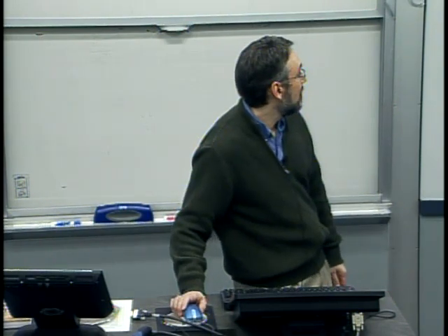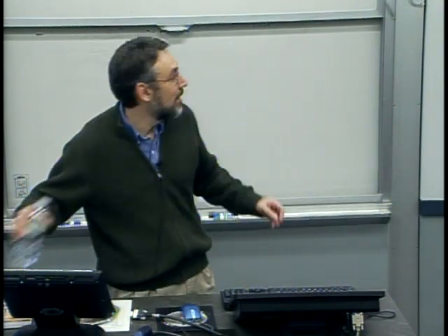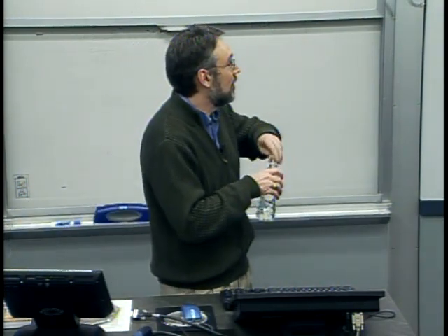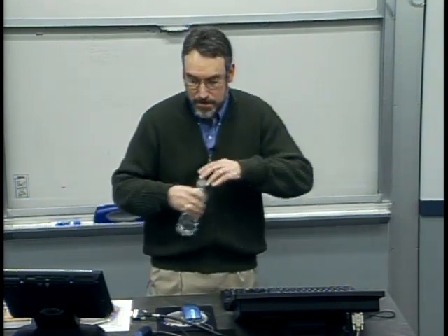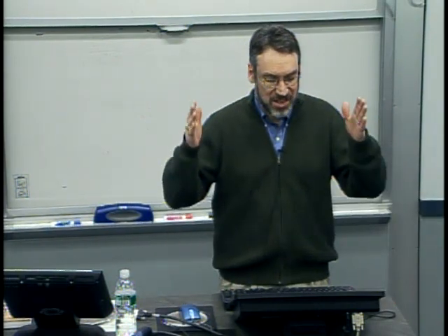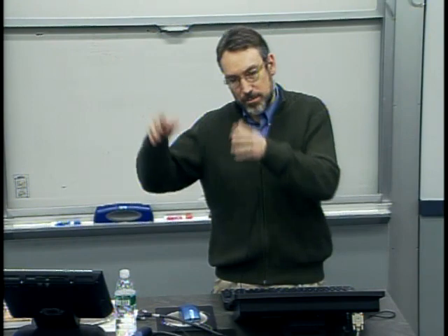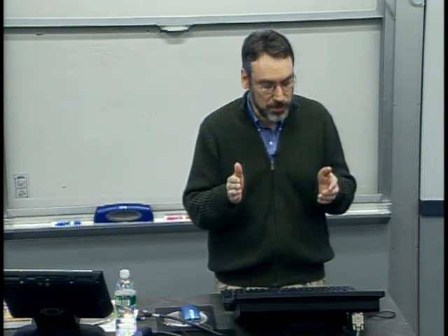Yeah, question? I understand the mask as the chromium, the black part. Right. The light won't shine through the black part. That's exactly right. So what we have is, the goal is to take some design from some CAD system or whatever that enables us to differentiate the surface.